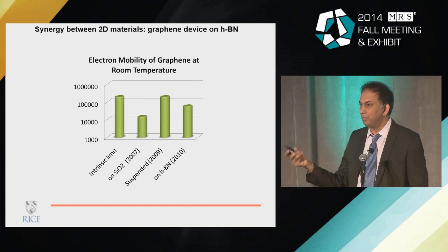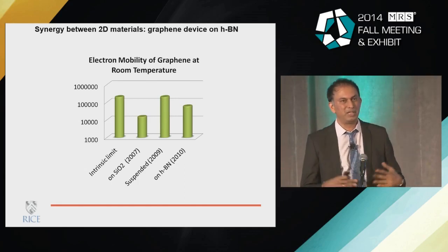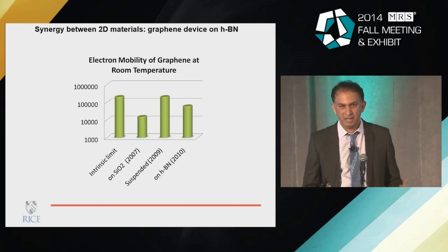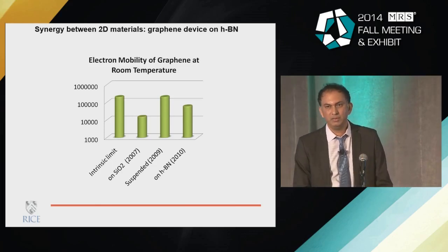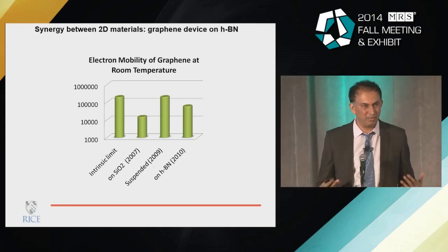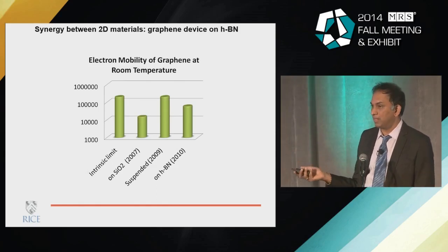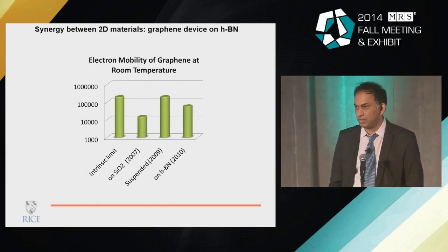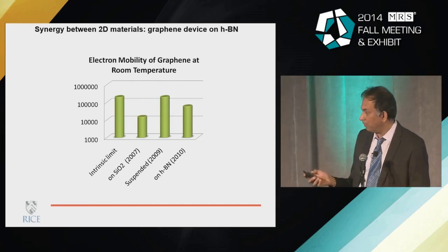So in order to really build the best devices, you have to have compatible material. So many times when you think about graphene-based or 2D material-based devices and structures, you are going to think about a broad range of materials that have similar formats, similar morphologies. So hexagonal boron nitride was really a boon to this field because people proved that you can use that substrate in order to get good values for device performance.